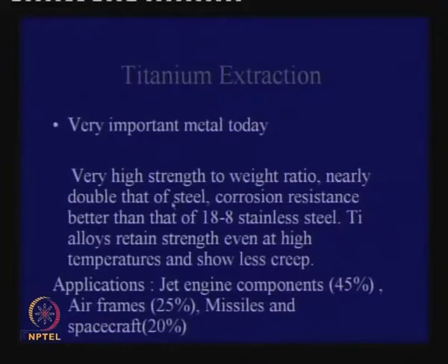Titanium needs special importance, emphasis, because it is a very important metal. It has many properties that attract all metallurgists, very high strength to weight ratio, nearly double that of steel, then corrosion resistance better than 18-8 stainless steel. They retain strength even at high temperature, show less creep.